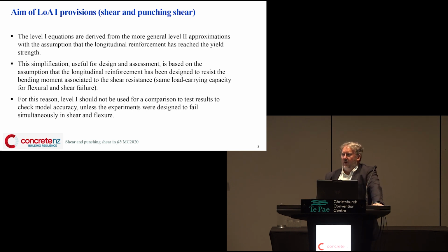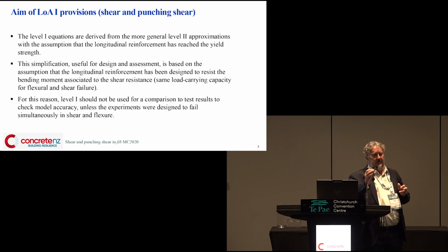But we want to do higher levels when you've got assessment of an existing structure, right? Particularly if you've got non-compliant detailing. We don't want to start tearing down structures just because of that. So in those cases, we may want to put more energy into it and go to a higher level of approximation, or even to numerical modelling.